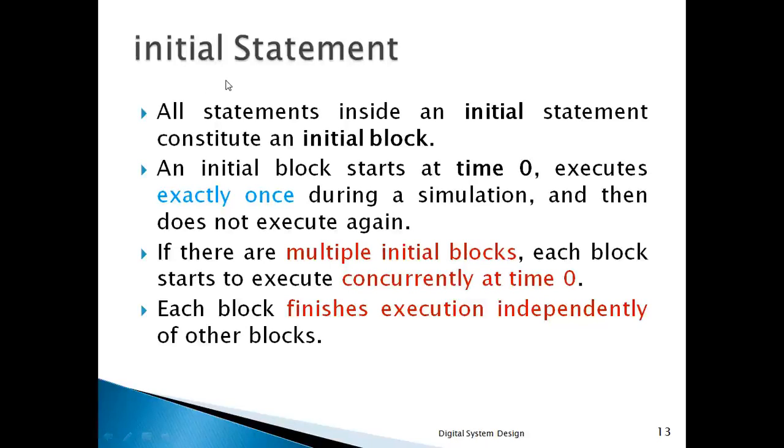Now here the detail of the initial statement is given. All statements inside an initial statement constitute an initial block. An initial block starts at time 0, executes exactly once during a simulation and then does not execute again.